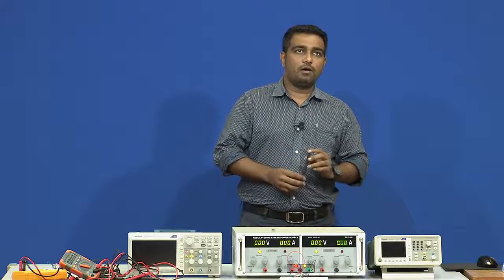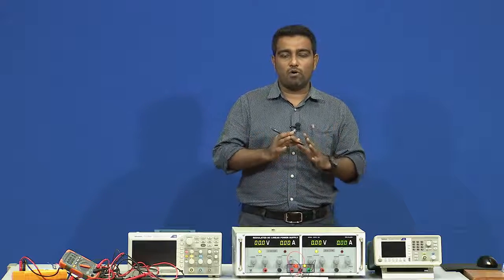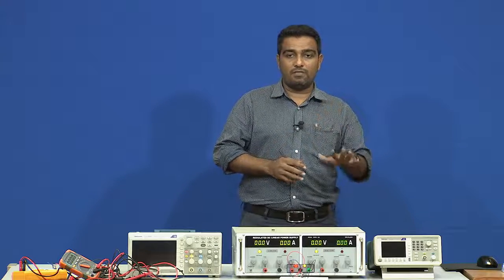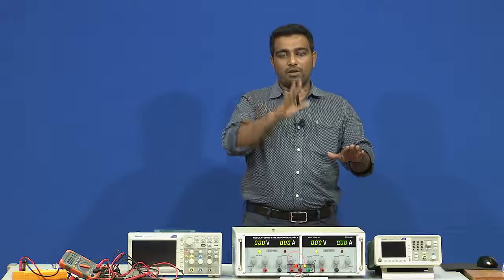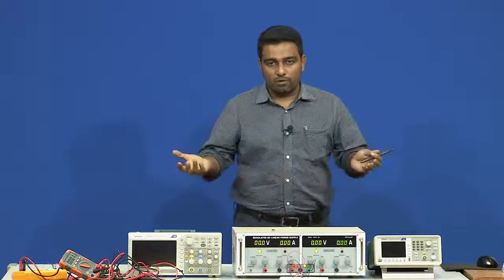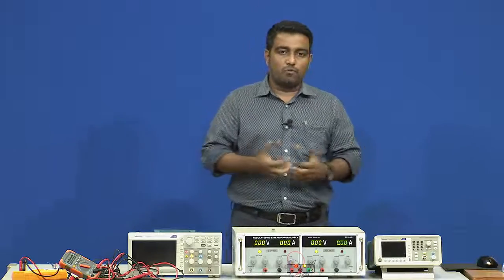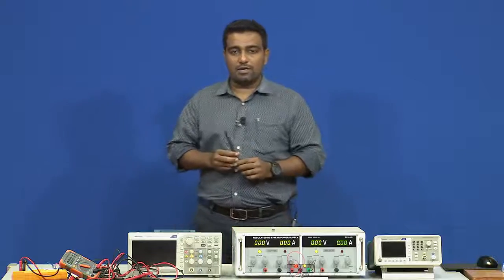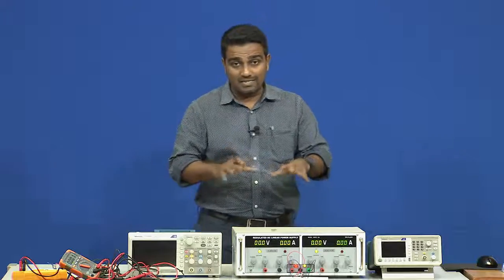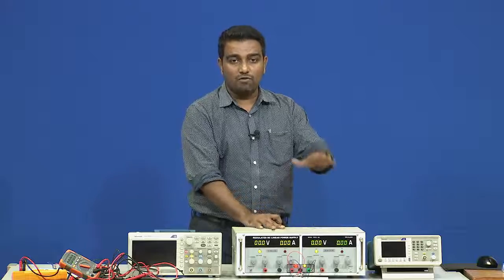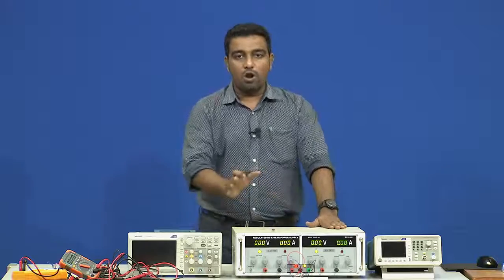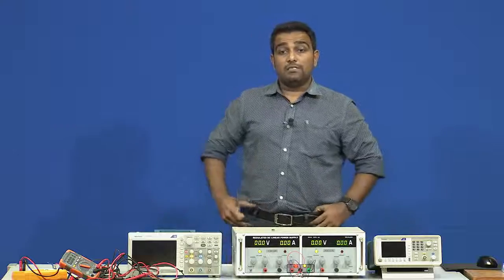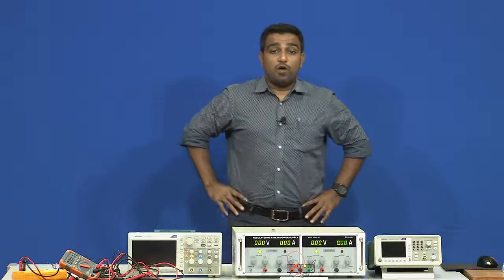Now, assume that you have given no voltage at input terminal, or the input terminals of the op-amp are grounded. That means inverting terminal is ground, non inverting terminal is ground. So, what do you expect at output? Output should be 0, right. But when you actually measure the operational amplifier by testing this particular experiment, that is, you give inverting terminal ground, non inverting terminal ground, and you measure the output voltage, what you will find is that the output voltage is not 0.